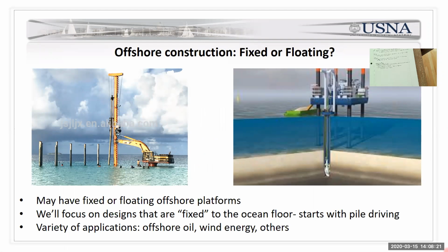The first question you have to ask yourself, there's two main flavors of offshore construction. There's fixed, which means you have a pile that's driven all the way into the seafloor, and the platform is fixed to the seafloor. So that's sort of what this artist rendition of this platform is over here. You see them driving some piles into the ocean over here. There's also floating platforms, which are often in very deep water, and they're sort of counterweighted. Very cool, but outside the scope of this course.